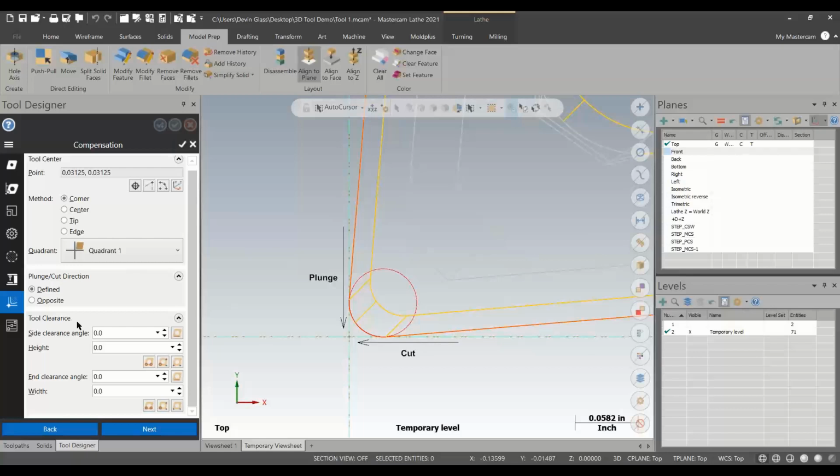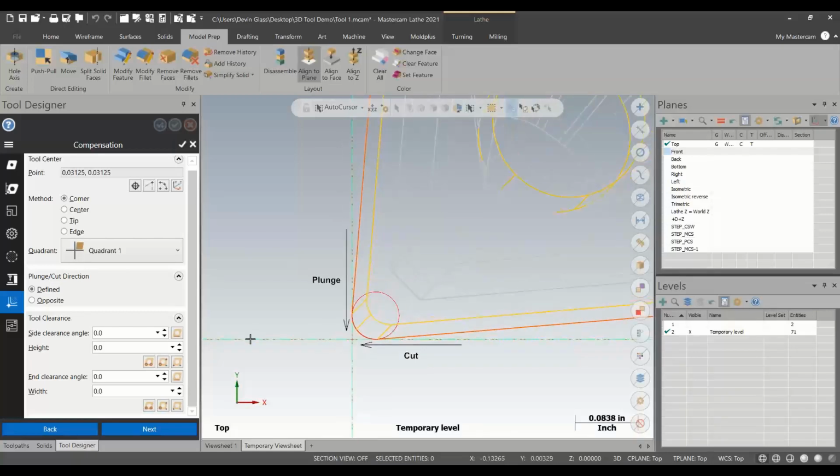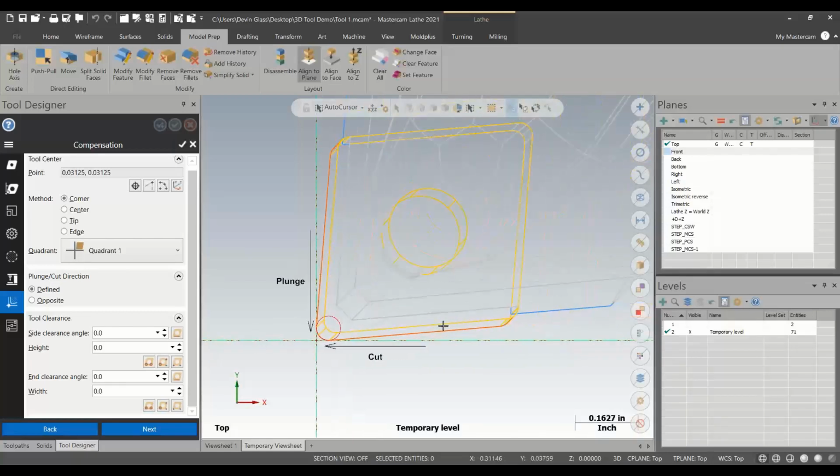And when you get into grooving tools, this is literally what it's using to determine the width of that groover. So when you're using a groove toolpath, it would determine the step over and all that for you. So we want to be super accurate with this because this is going to help us in the long run make sure that we're not gouging into material when it comes to the sidewall. Because right now it doesn't know that these walls exist, at least toolpathing wise.